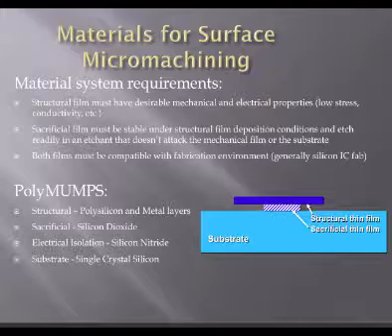Okay? So you got to have low stress materials, and that was a big issue when they started making polycrystalline structures, because in the old days when we did polycrystalline for computer chips, they were all glued down basically, right? The stress didn't matter as much. But now if you make a little part and release it, it's going to bend.